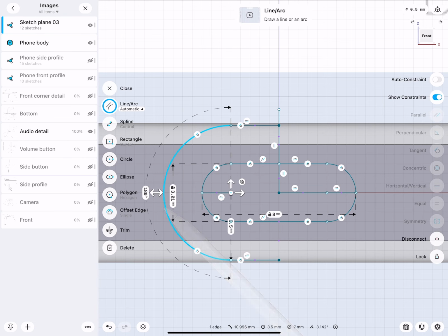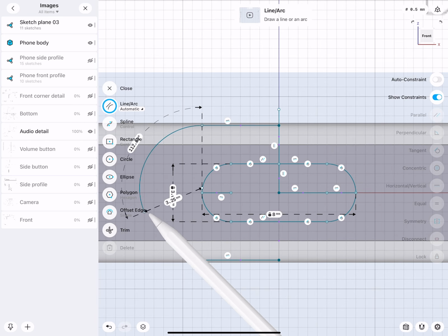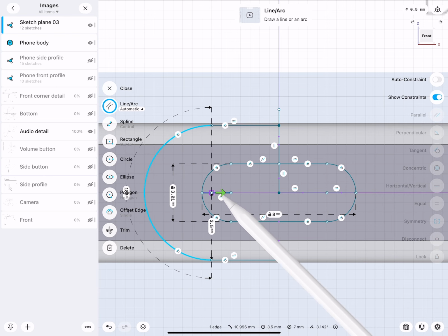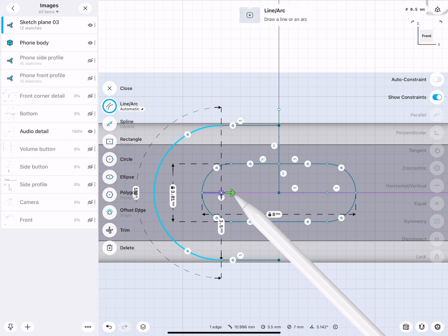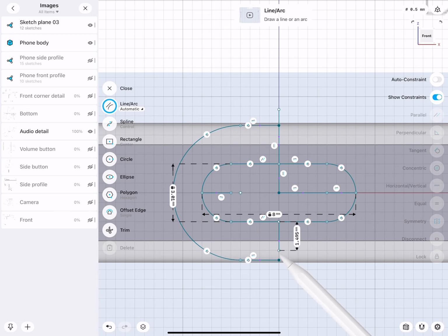And if we remove this, here also, there is a midpoint there somewhere. So we will simply circumvent it this way. Bring this over. New arc. There. So this point or this arc was locked in there, and that was basically the problem. So I will keep this to there and draw a line down.